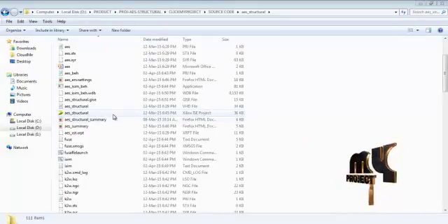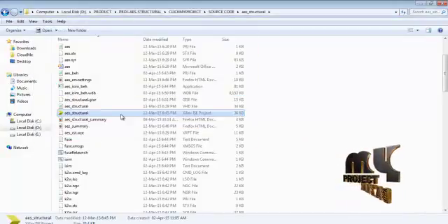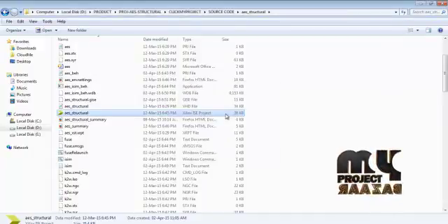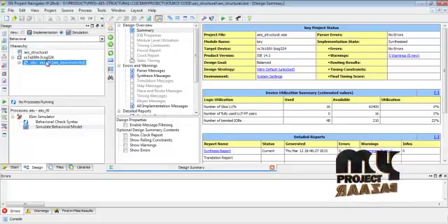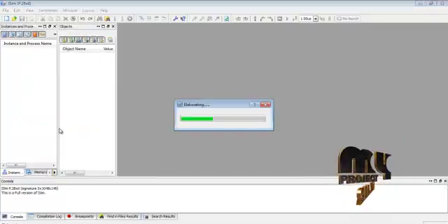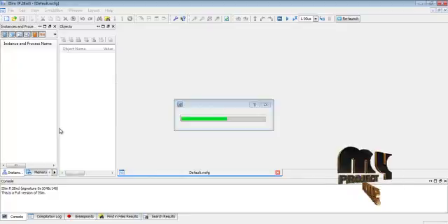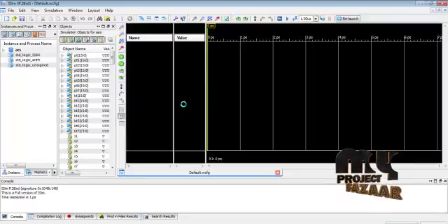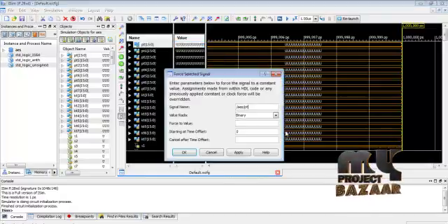Next we see the final output for the product. First we run the AES structural designs in the Xilinx ISE Project Navigator. Then we select the simulation process and run the simulate behavioral model for the 128-bit AES architecture results. Then we apply the binary values for the plain text and the key text functions and process the AES architecture result. This ISim project simulates our overall process. Then we apply the binary pattern results for plain text and key text functions.